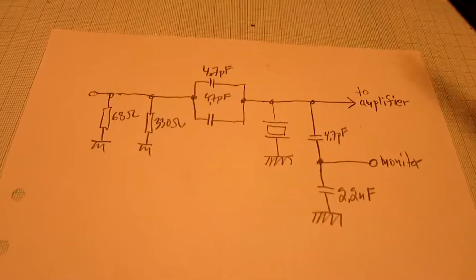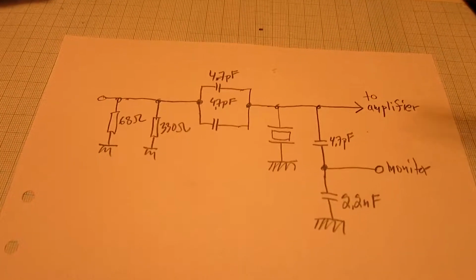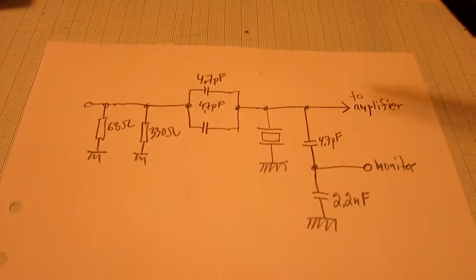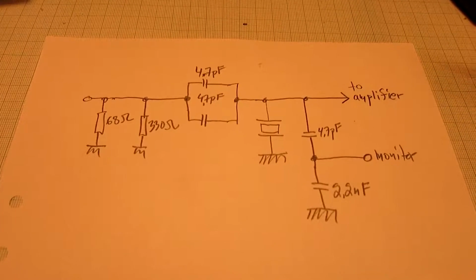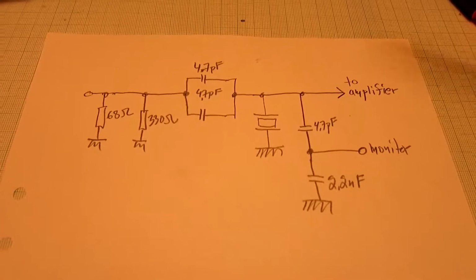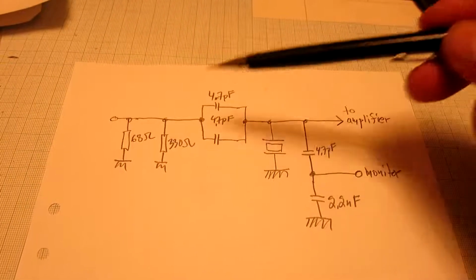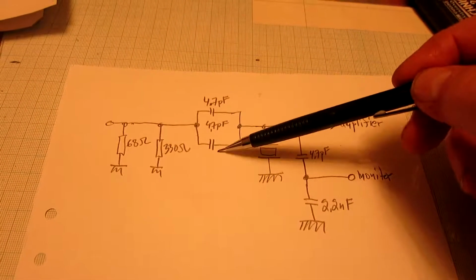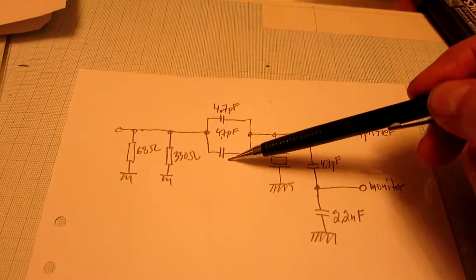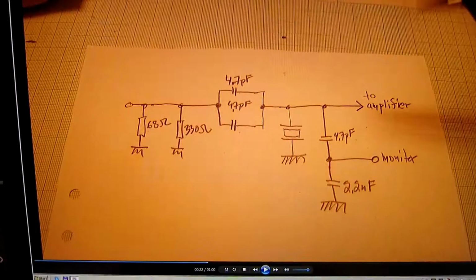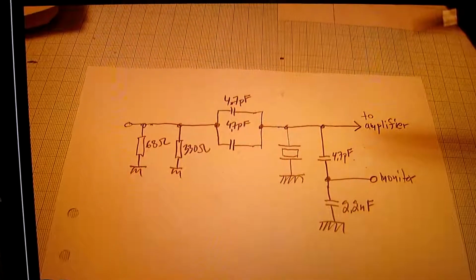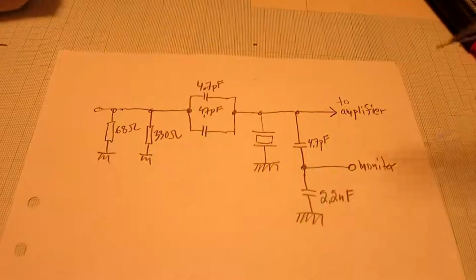To investigate the properties of the crystal, now that I have it operating on the proper temperature, about 65 degrees, these two resistors in parallel, and with these approximately 10 pF coupling, presents a 50 ohm impedance on the resonance.